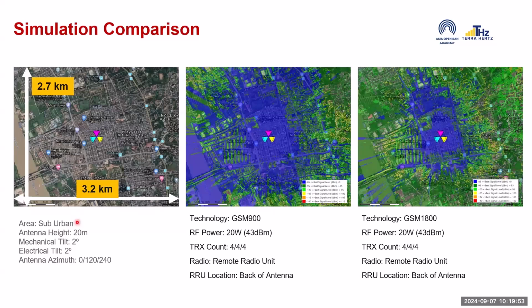If I will deploy in provinces, like yung mga bahay ay layo-layo, scattered villages, so probably one house is 100 meters from another house, and then 200 meters from the other house, and then 300 meters from the other house. If I will build a cell site there, what frequency am I going to use? Is it 900 megahertz or the 1800 megahertz to provide initial coverage?